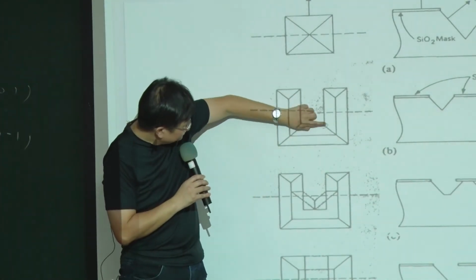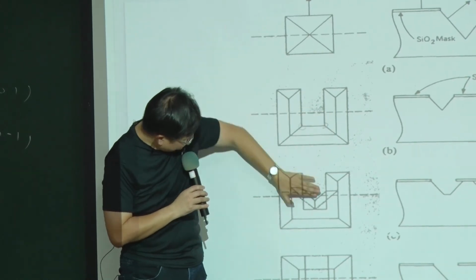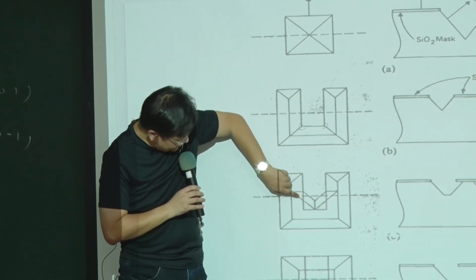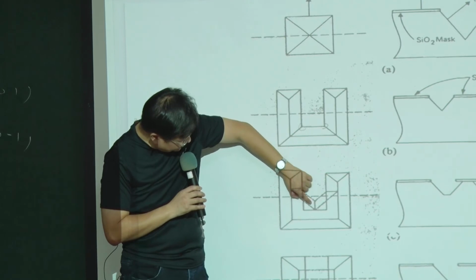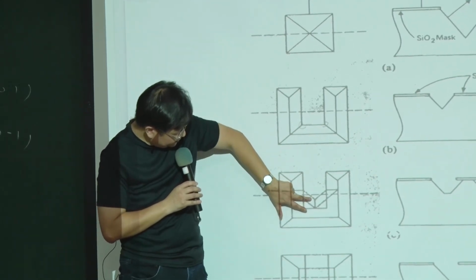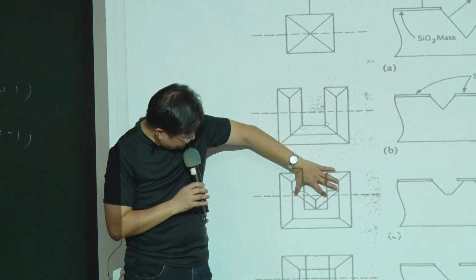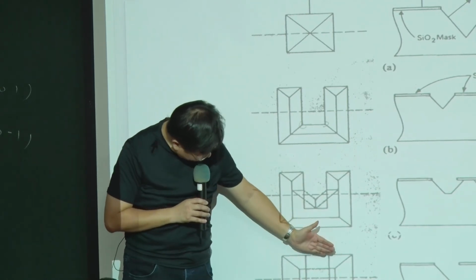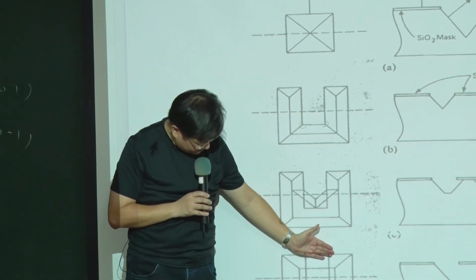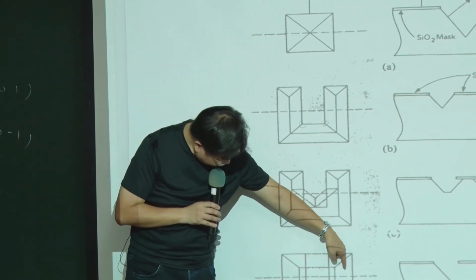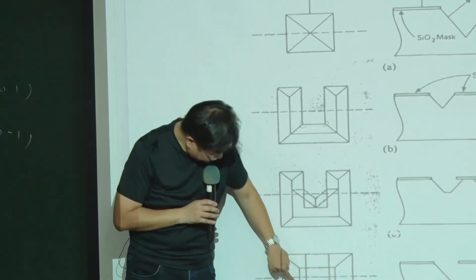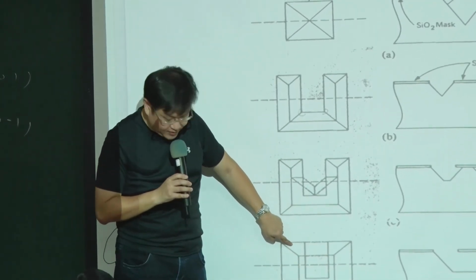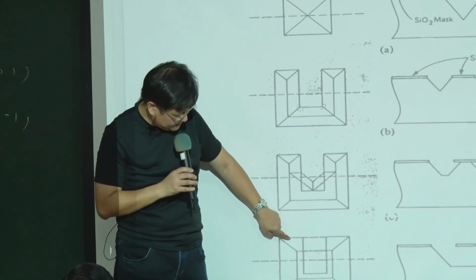That's the top view. These two surfaces will retreat to the other surface, and as time progresses, these two surfaces are still extrusions to the outside, so they cannot protect the surface very well. So it will finally be etched away until the final 111 surface forms here. This 111 surface will form a very good structure with the other three 111 surfaces to protect the final structure, so the final structure will be fixed without further progress.